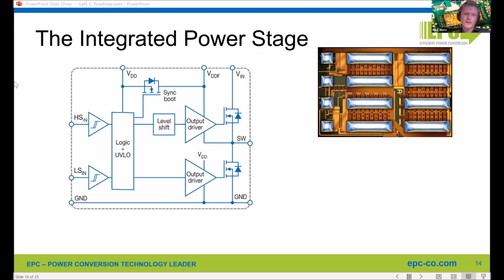That's really up to the PCB design and the system level design, 3D integration. How well can I fit my decoupling cap as close as possible? In that sense, it's a multidisciplinary question, right? This is a piece of the puzzle that needs to be solved, and that is being solved, like in this nice example. But you also need to attack it on the system level. Agreed.